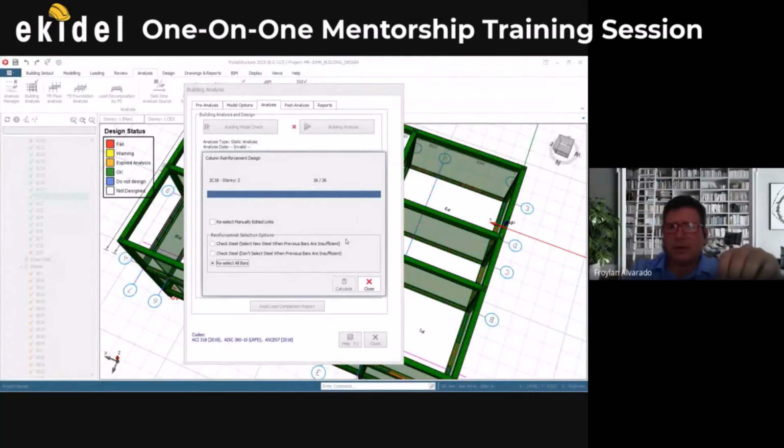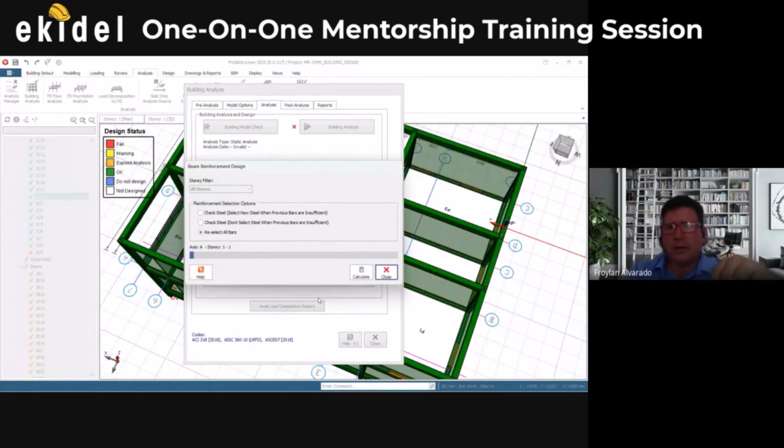It's almost similar to this one, no? The one thing that I'm also doing is checking to see how I can do the one with AutoCAD, then bring it in, then see how it plays with ArchiCAD, and then see how I can create a streamlined ArchiCAD. So just like how you showed me that it can't model the slabs, what I'm doing now is modeling only the beams and columns, and I'm inserting the slabs in ProtaStructure, no? So it seems to work.